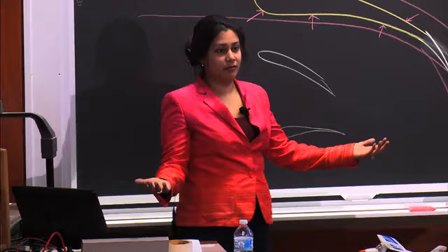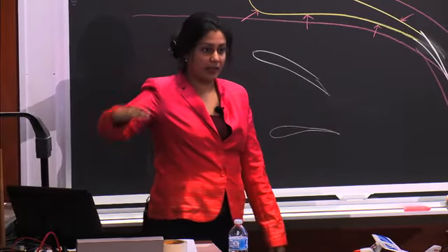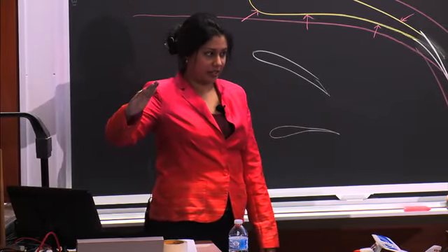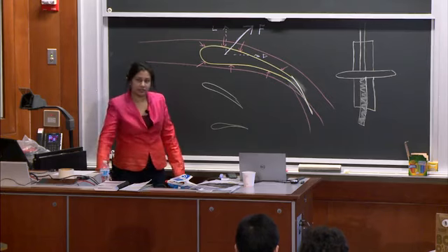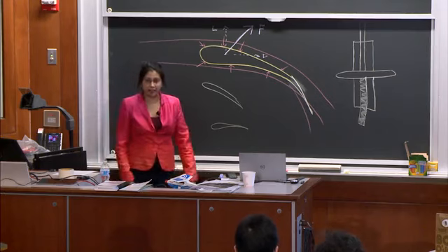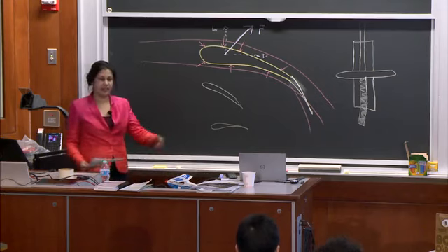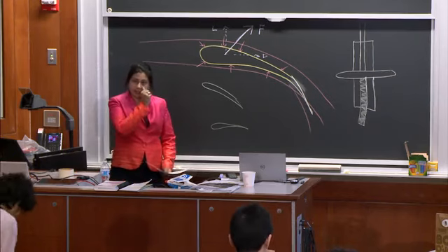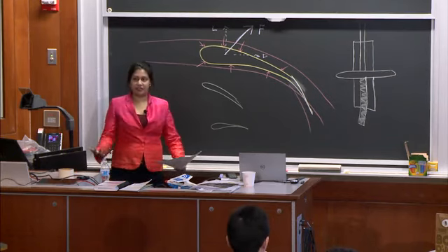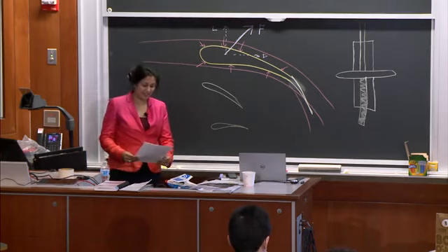So that's really all that angle of attack is talking about, that if you angle your hand up, it gets pushed up a lot more. If you angle it down, it gets pushed down. That's the angle of attack. And we're going to define it more specifically when we talk about the terms associated with an airfoil and the shape, but it's good to get the general concept first.